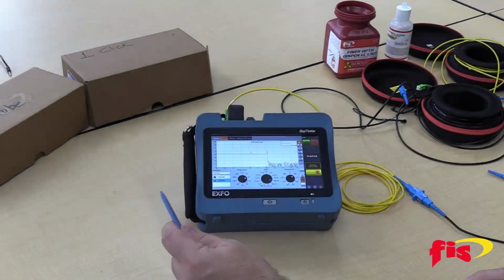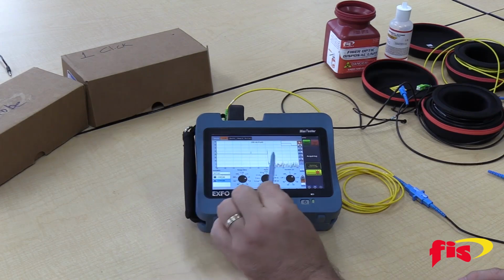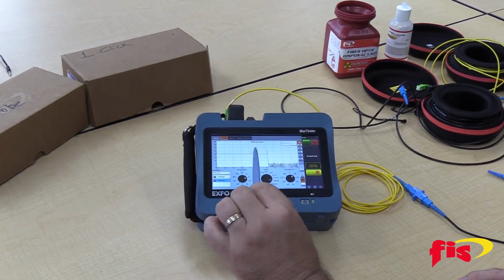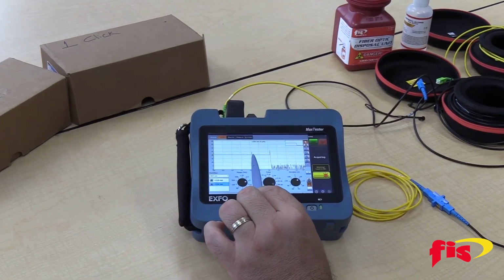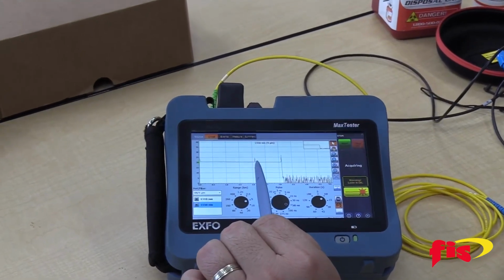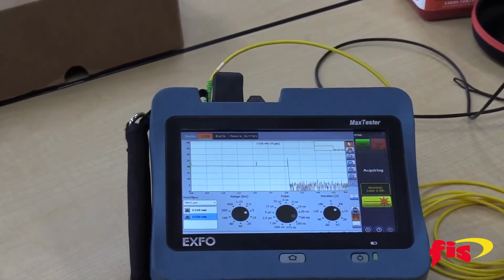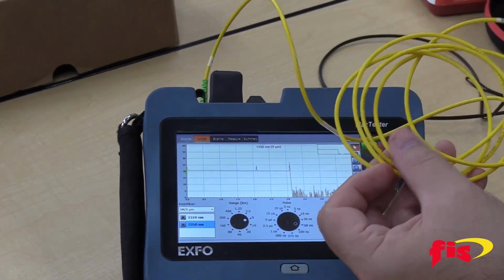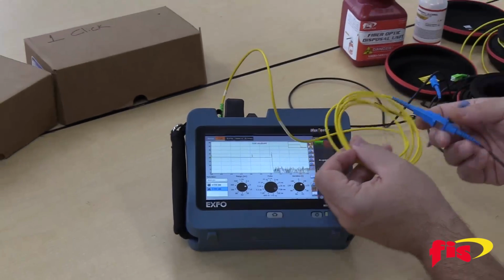All right, now that we're set up at the OTDR, you can see I have a trace running on my box that's about 3.2 kilometers long. It does have a reflective event in here. I've got it on real time to show you. So we talk about these spikes and how they have widths. Now, one of the questions: how long should my pulse cable be? You can see here I have a short patch cord plugging into my box.